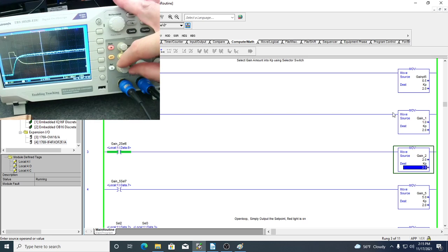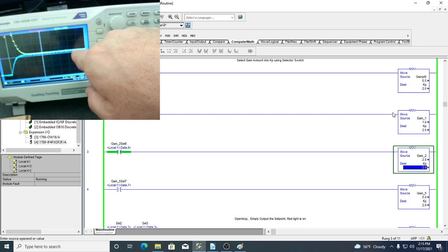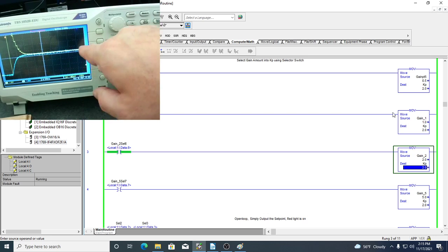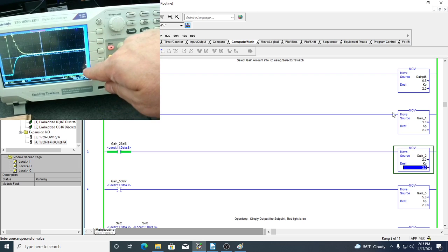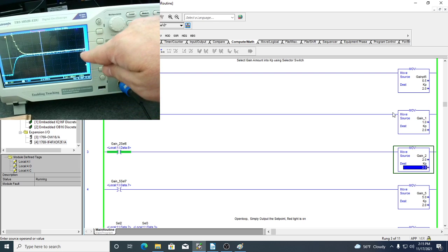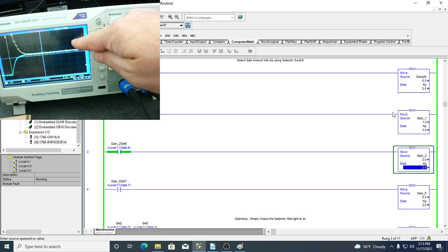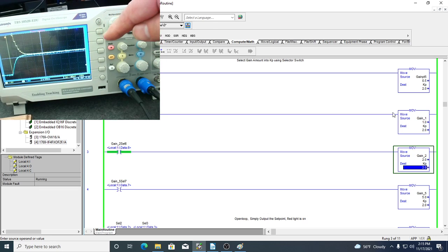Okay, now remember, it actually is coming down to my steady state value here, in this case to hold the capacitor at that voltage. But again, the capacitor should be at 5 volts. Okay, so it should be at 5 volts, so it's still only at about 3.3 volts. So I still have steady state error.